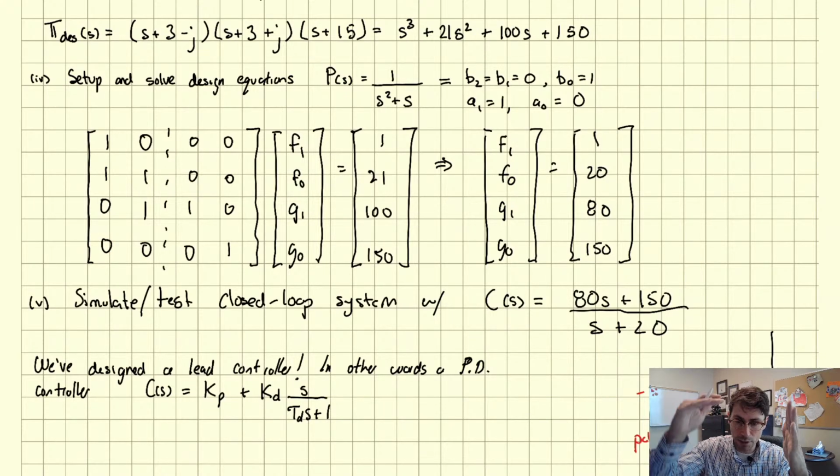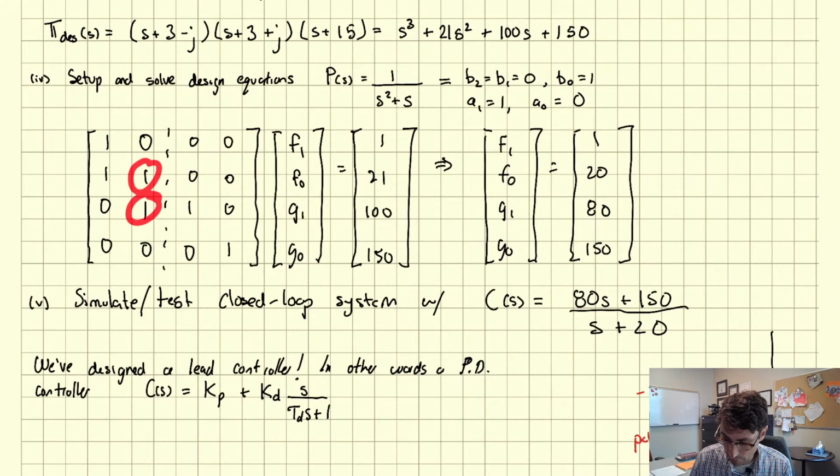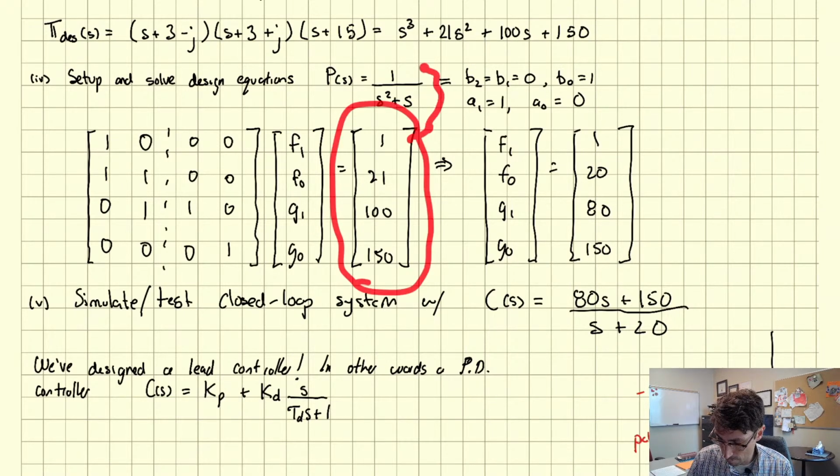Second column is I take that first column and I just shift everything down by 1. So this is the padding of a 0. Now, first coefficient, second coefficient, third coefficient. Now this indicates that we switch over to the numerator. And so now I use the b's. So b2, b1, b0, pad with zeros. Shift everything down 1. So this is my padded 0. And I've got b2, b1, b0. So that's the matrix. It depends only on the plant. And then this here came from the desired characteristic polynomial. So I've just listed the coefficients of that polynomial in that vector.